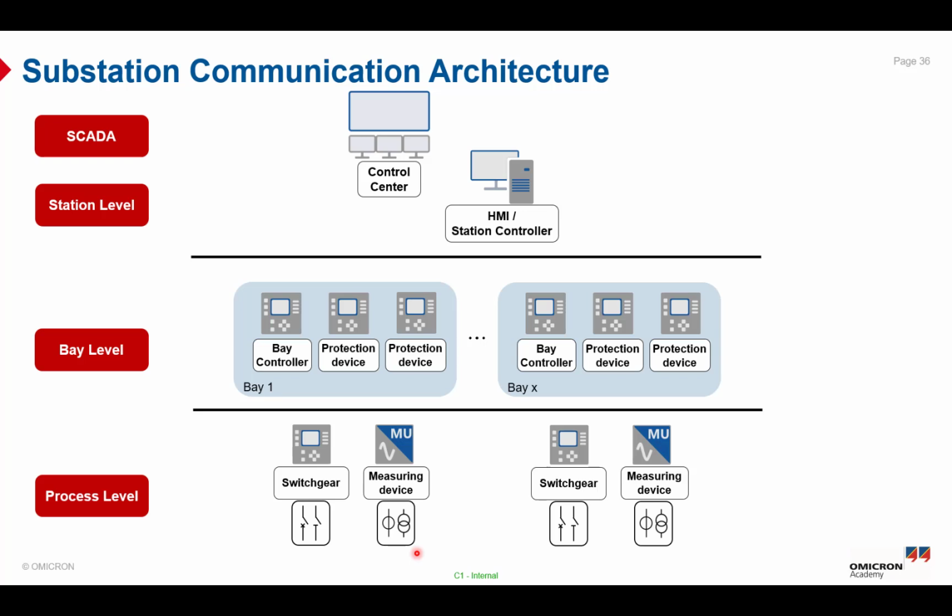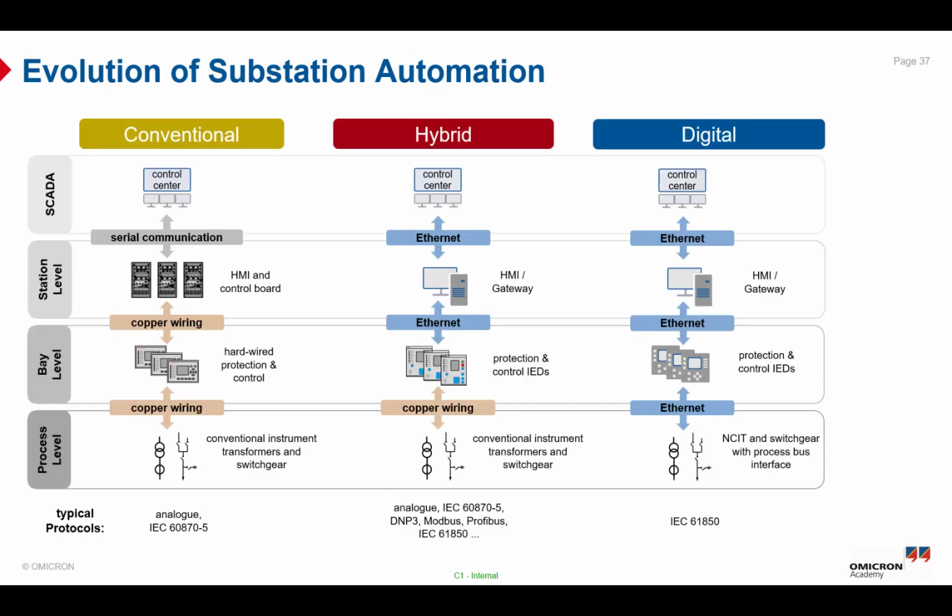So at the bay level, we have a bay controller, we have a protection device, and many more IEDs. And on the station level, you will find the HMI, substation controller, and we have also the control center in the SCADA level. So here is the hierarchy or the architecture of the substation communication.